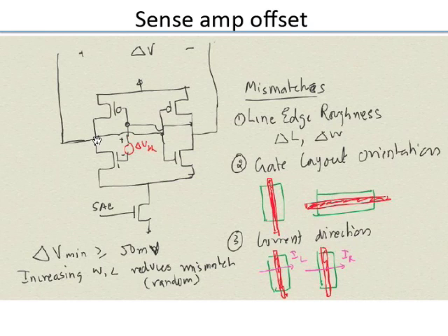Let us say on the left side the voltage remains at VDD, but the right side the voltage goes down by a delta V, maybe 700 millivolts. When you turn on the sense amp enable signal and start pulling this node down, the right side voltage is connected out here. So the right side voltage goes to the left side NMOS transistor and it is lower.